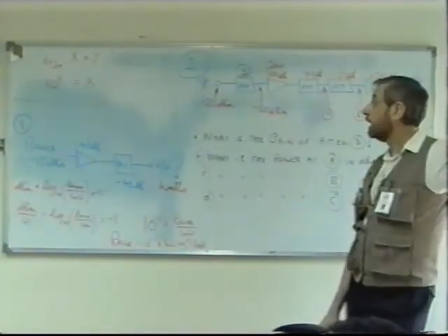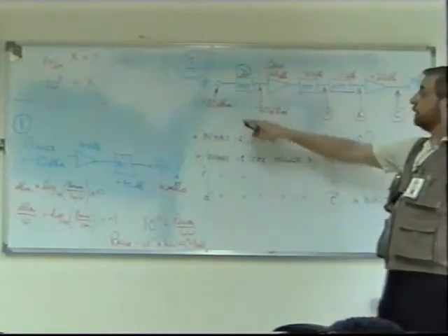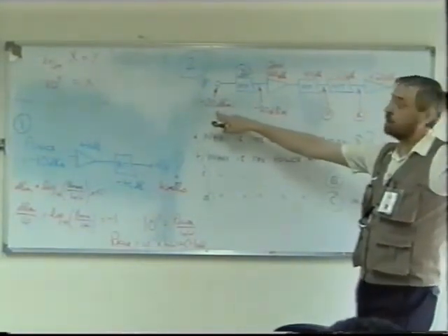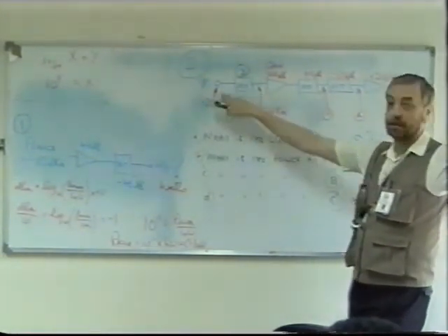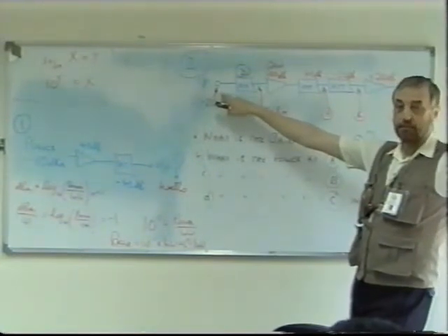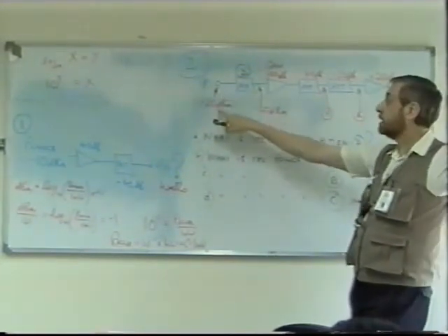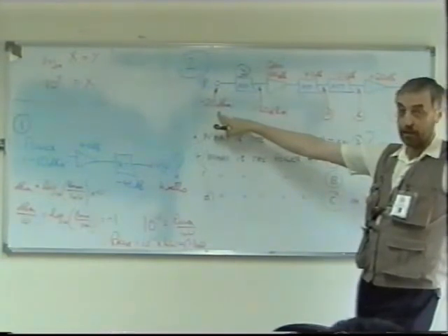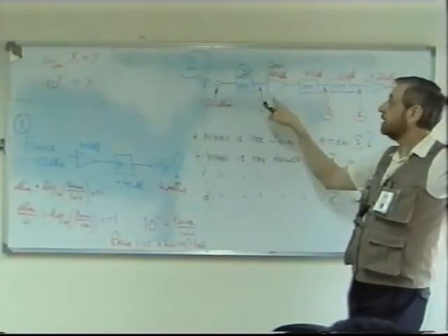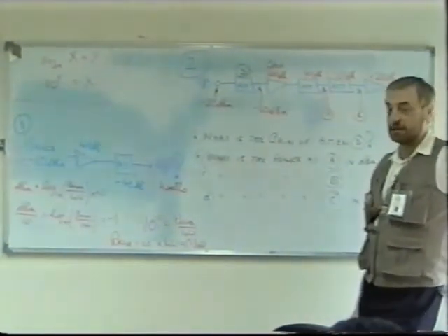Yeah, so it's going to be a negative number. Well, we begin here. You see, I've made it quite easy. I haven't put a power input and output here in terms of watts. I've put it in terms of dBm. So now it should be much easier to see what the gain of this attenuator is.